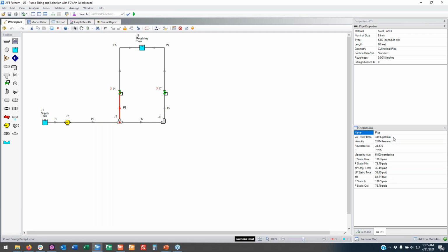our flow moves along this left leg that has no losses at the control valve, while no flow moves along this right leg. And that's pretty different than what we might expect for a Newtonian fluid. However, for this Bingham plastic, where there is that yield stress, this is somewhat expected behavior. This is telling us that when the fluid is moving along a single flow path, we can meet and exceed that yield stress. However, when we have these two parallel flow paths, we no longer can meet that yield stress.